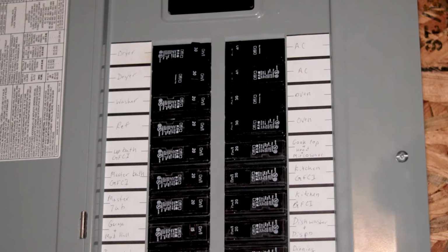Make sure you go and check that your air conditioner and HVAC unit breakers haven't tripped. This would indicate a larger problem. Finally, open up the inside unit and make sure the wiring looks good. This is a little bit more of an advanced troubleshooting step, and I'm not going to go into that in detail here. But if it does happen to be your fan, this is an easy thing to replace. Unbolt it and replace it.